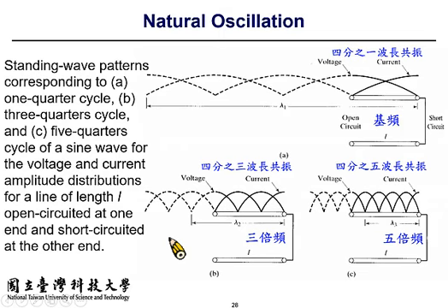Then the boundary condition can be satisfied, which means the same piece of transmission line can support another resonance, which happens to be 3 times as high as the fundamental resonant frequency. A similar result can be observed at 5 times the fundamental frequency, and at this time the length of the transmission line is 5/4 of a wavelength.